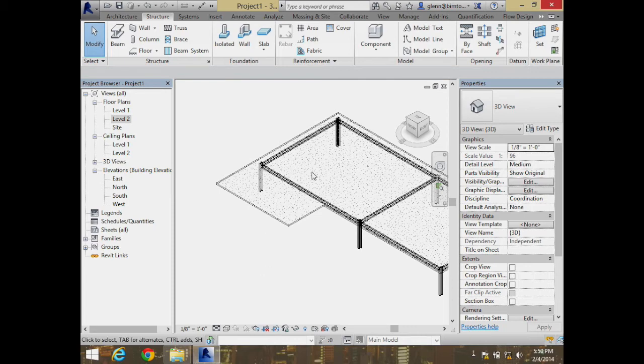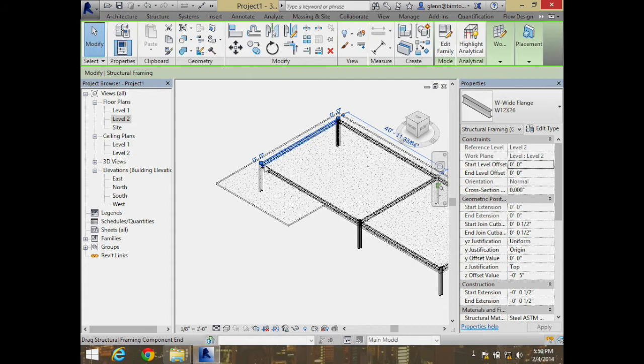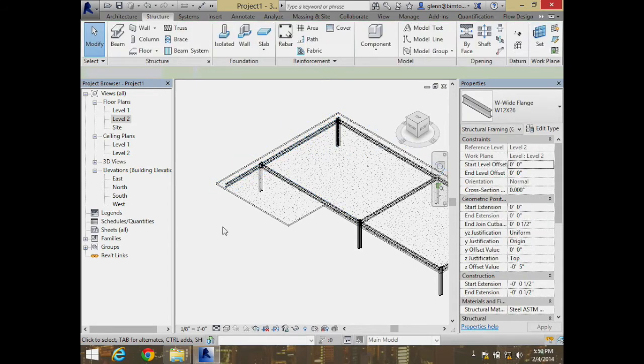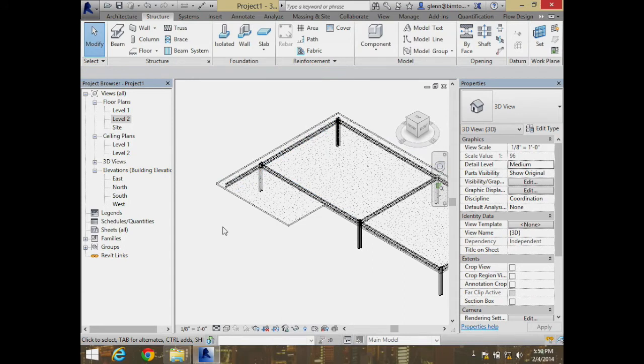To the extent that I want to take this one and just drag it on out, that's actually pretty good in terms of what's going on. If I am going to have it dragging out there as a cantilever, I'm going to have to change my column a little bit, though. It can't go up through the beam. It's now going to have to come underneath it, and that's going to be okay in the scheme of things.